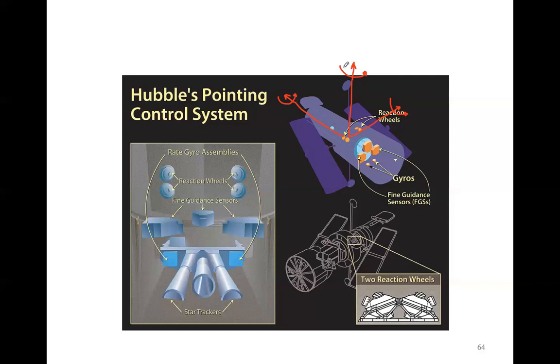So the requirements on these two axes are really important. That's the reason why the position of the star tracker is aligned to the position of the telescope, because, as we said, the axes orthogonal to the boresight of the star tracker are the axes that you can determine with a more accurate precision.